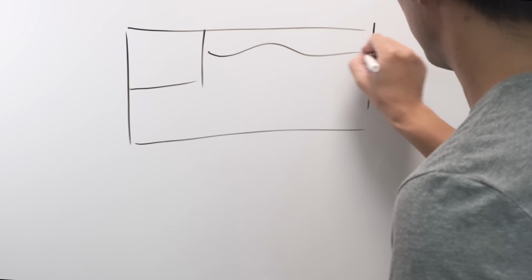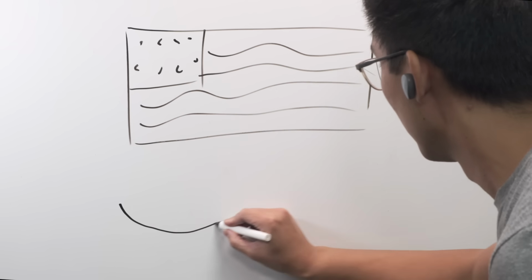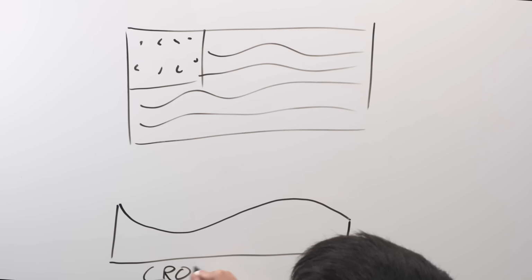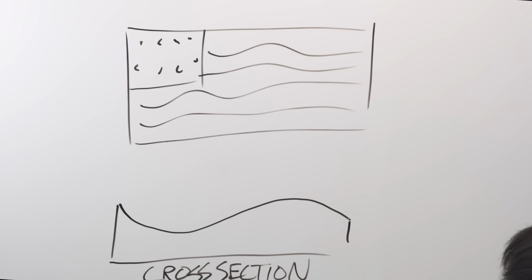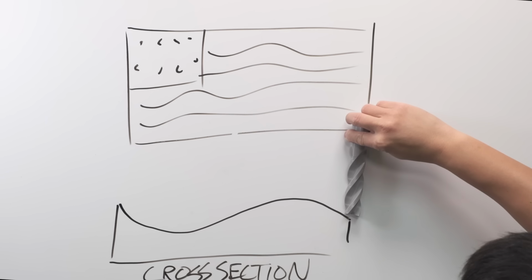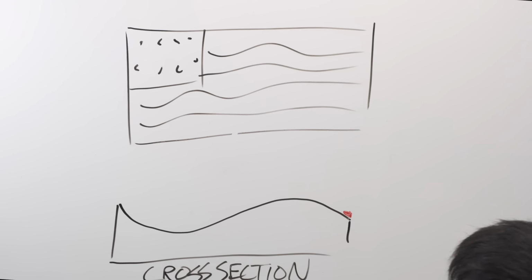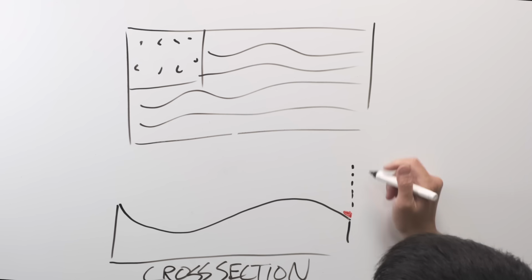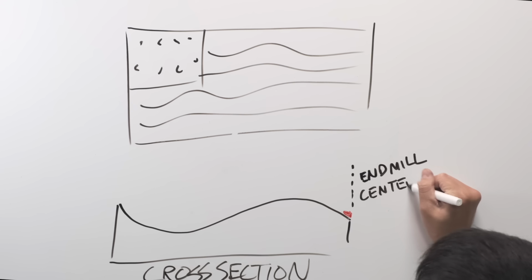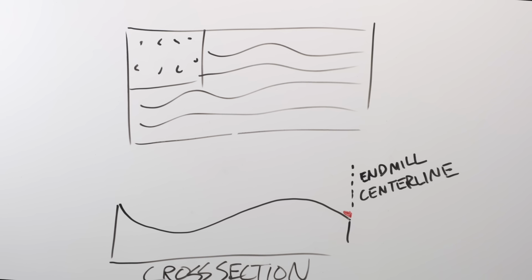Side note, you can also get puddles of leftover material at the edges of the flag too. When you select the bounding box for a finishing toolpath, you're telling Carbide Create that the center line of the finishing tool must stay within this vector. When I picked the profile of the flag for roughing and finishing, this is what was happening at the perimeter.